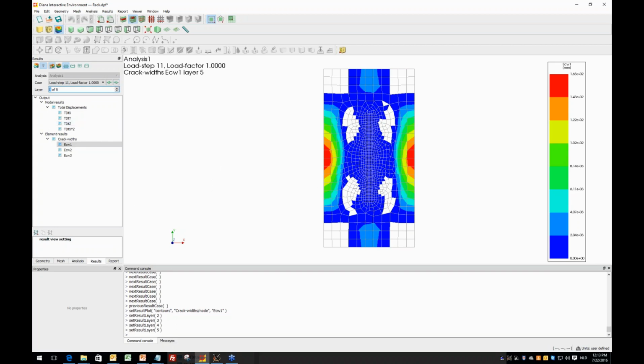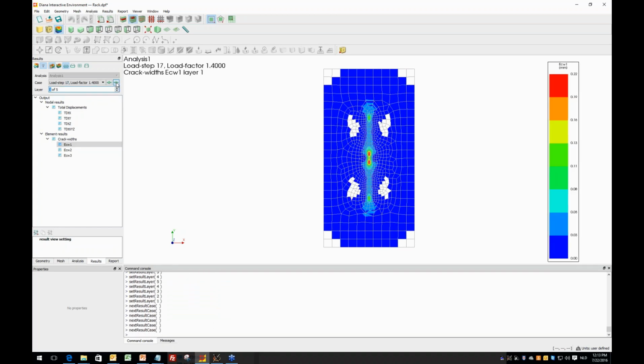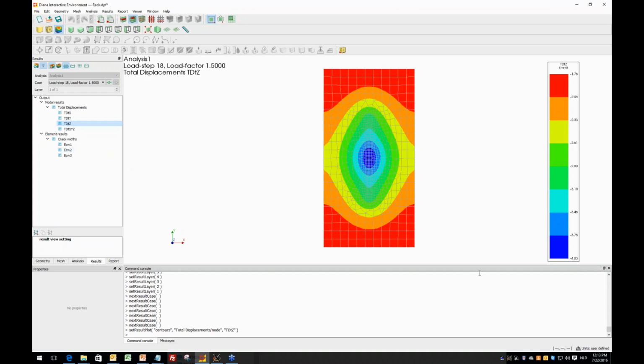And if I increase it towards the ultimate limit state, you see that it is now a principal crack width of a maximum of 0.24, so it's a little bit lower than with the smaller dosage. And the displacement is also now a little bit lower. It was minus 4.25 and now it is minus 4.